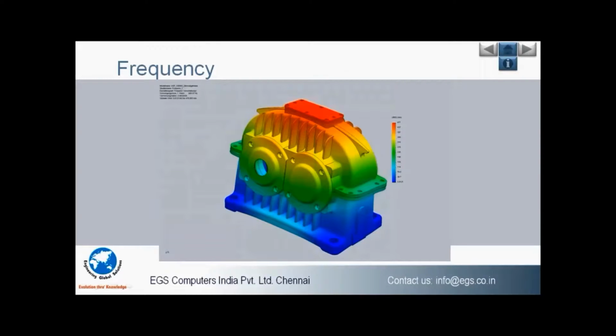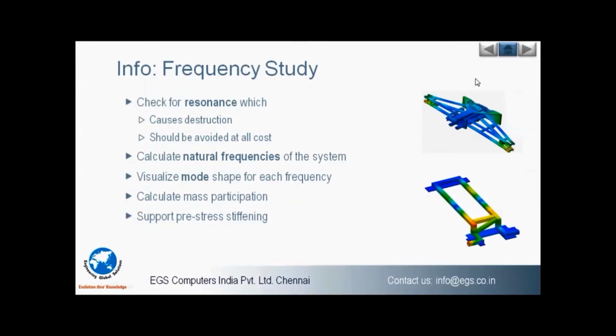The frequency analysis will be very helpful for the automotive, construction equipment, and material handling verticals. Vibration can never be eliminated from a system, but we can reduce it to provide noise reduction and a better life for the products. Using the frequency study, we can check the resonance on the product designs, since it is going to cause destruction. So we must avoid it at any cost during the initial product design stage.